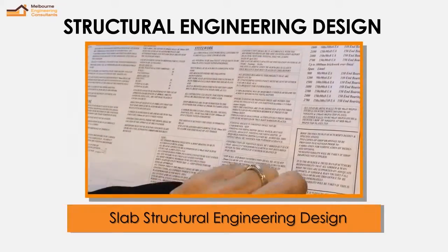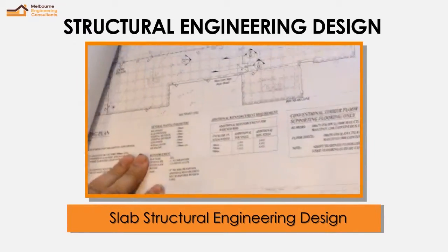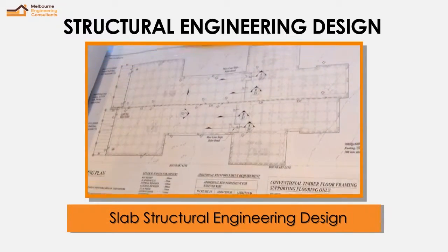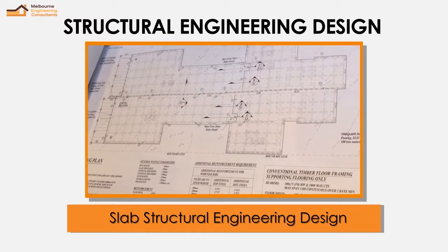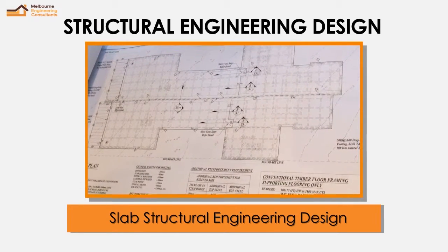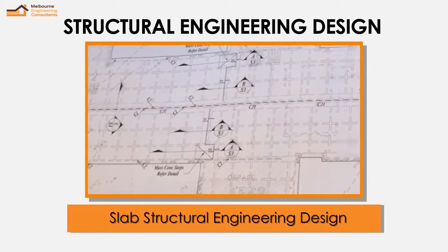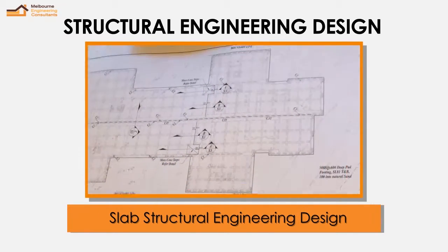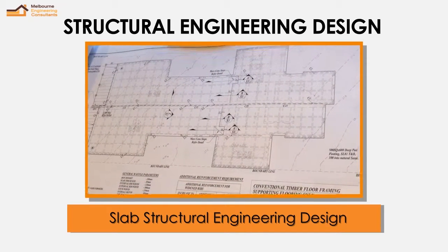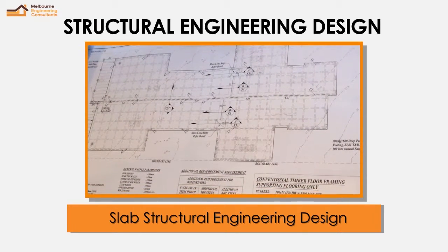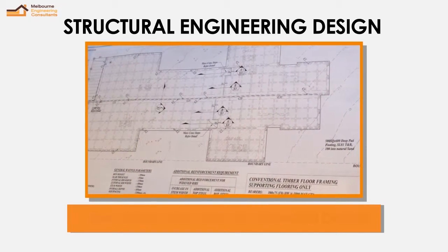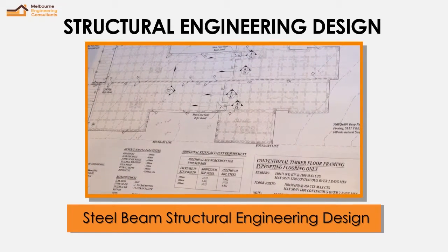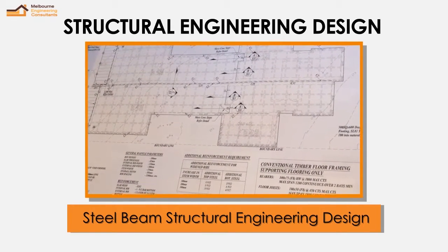On page number 2 we have the footing design which we have designed especially for this project as a waffle slab, which is of course economical and energy efficient in terms of saving power, because in a waffle slab we use polystyrene blocks and they are hollow, so you save lots of concrete, and not only the concrete but you also save the heat passing through the ground from the concrete slab. So it's like an insulation barrier between the ground and your concrete slab, which saves a lot.